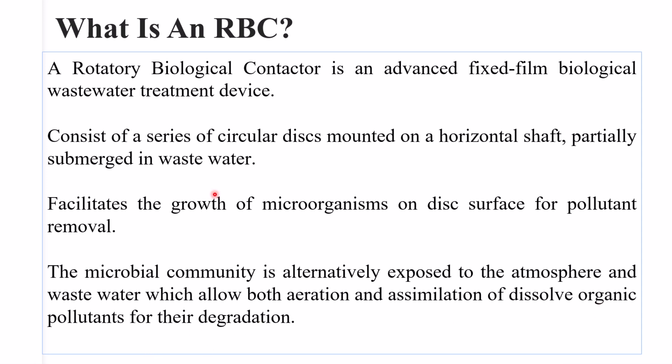Now imagine circular discs like giant CDs mounted horizontally on a rotating shaft, and these discs are partially dipped into a stream of wastewater. Now the magic is this: the microorganisms grow on the surface of the disc and form a thin biological layer which we call biofilm. As the disc rotates, the biofilm on the disc is alternately exposed to the air and then the water, and this allows the microorganisms to breathe and feed.